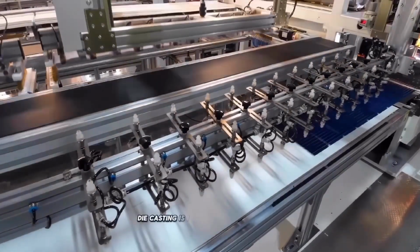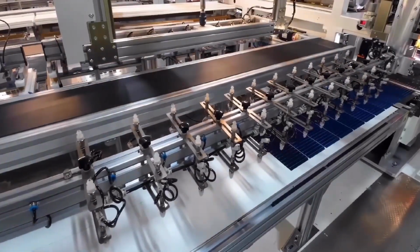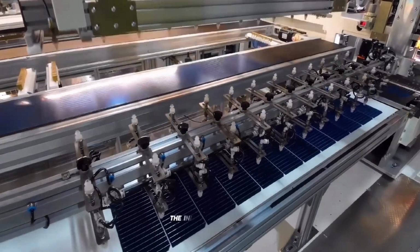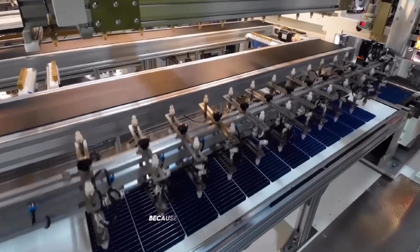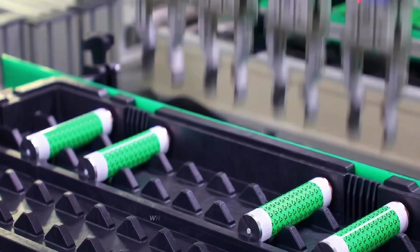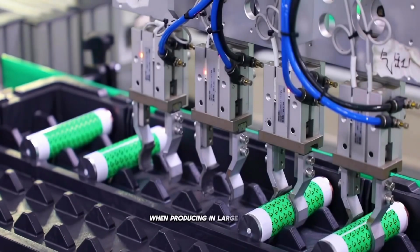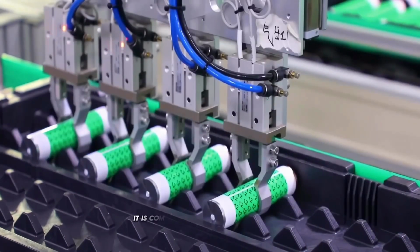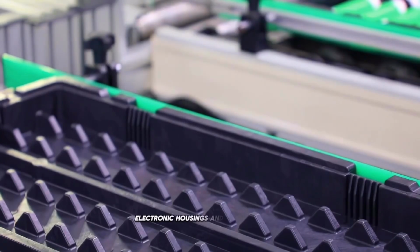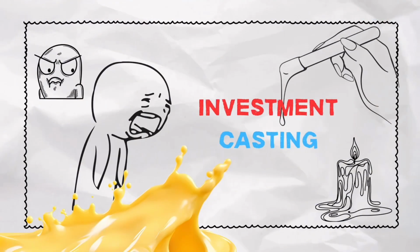Die casting is ideal for mass production and works best for small to medium parts. The initial cost is high because of the die and machinery, but the cost per part is low when producing in large volumes. It is commonly used for automotive parts, electronic housings, and industrial tools. The last process is investment casting.